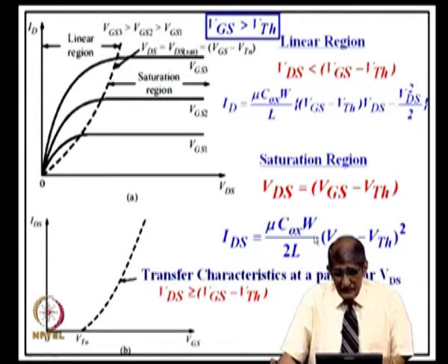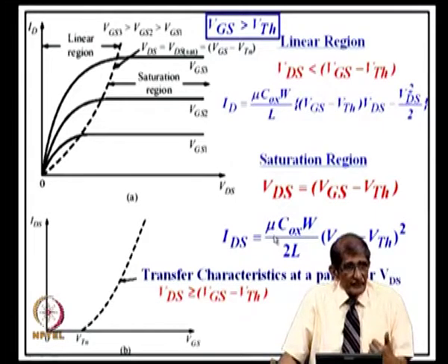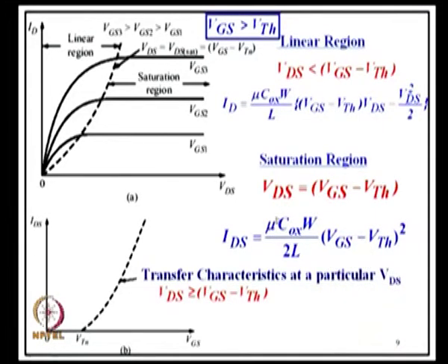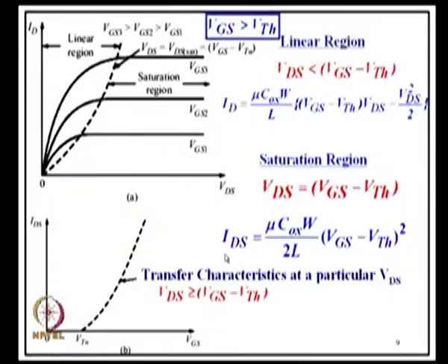So, from here you can see that we get better current, better performance if the mobility is high. So, from here you will say, I would choose a material which has got high electron mobility or high hole mobility. Very indicative of this is that. And of course, you want to have larger ID. Why do you want larger ID?